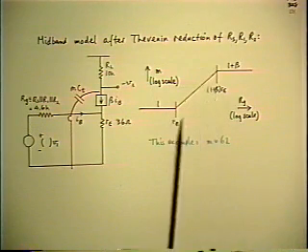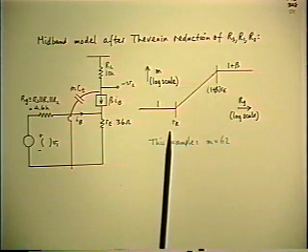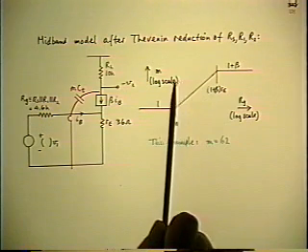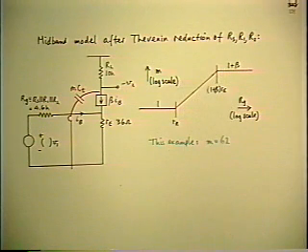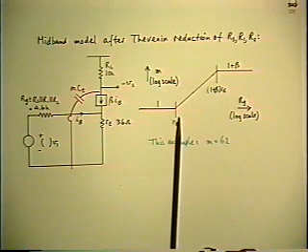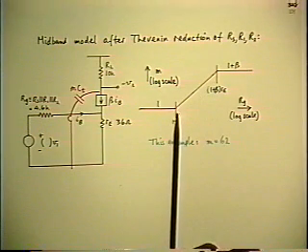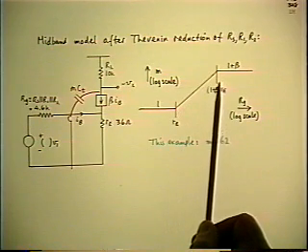But notice you get another important piece of information out of this. You get corner resistances, just like corner frequencies. And here are the values. The lower corner resistance is RE. The higher one is 1 plus beta RE.